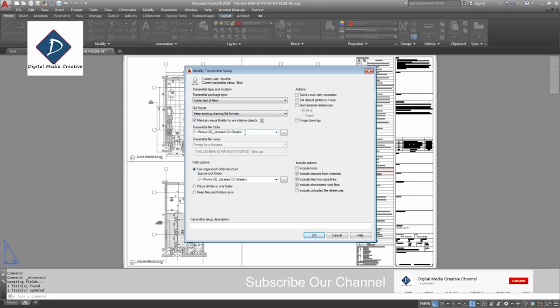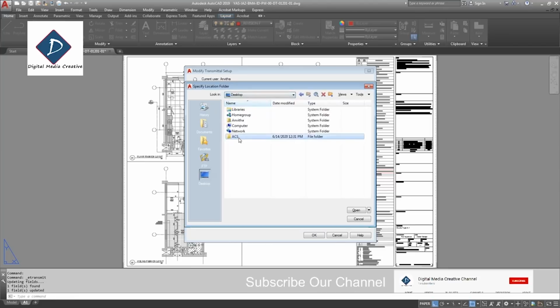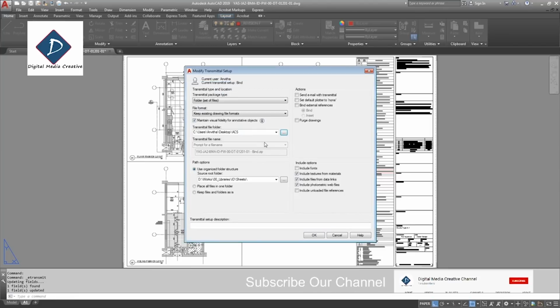Then for the transmittal folder, I'm going to select one folder on the desktop. For the path option we can see three options. One is use organized folder structure, root folder, which means it will replace it in the same folder. The other one is place all in one folder, which means it will go to this transmittal folder.